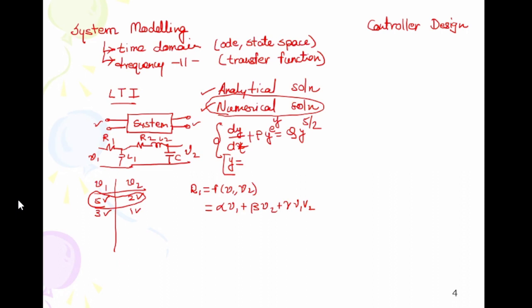That you cannot directly correlate one parameter with the input and the output of the system, because a large number of parameters are there and there is a coupling in between those parameters. So in that case, how will you be able to get the value of R1, R2, L1, L2, and C? Since the analytical solution is not known to us, you have to go for the optimization-based approach. So by applying an optimization-based approach, you would be able to get the value of the parameters of the circuit, or you would be able to get the transfer function of the system from the input-output experimental data.